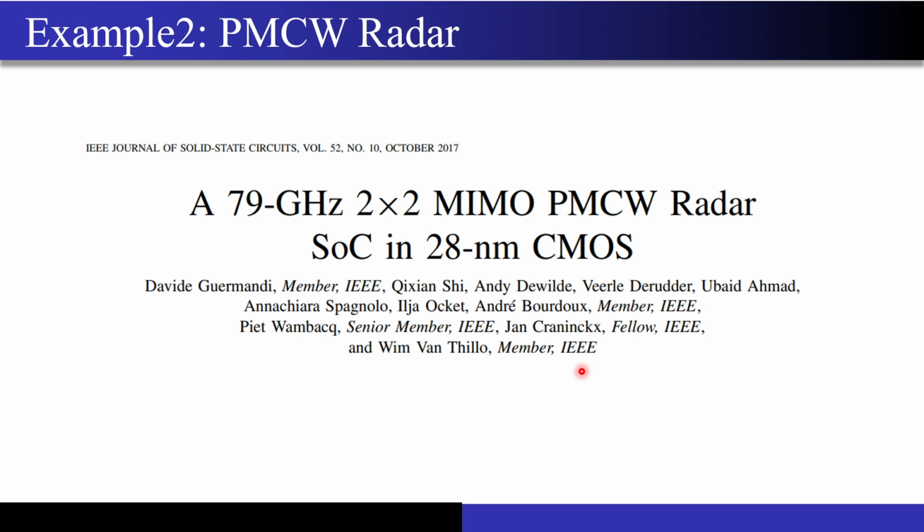So now if I move on to the next radar, that was the FMCW radar and this is a PMCW radar. What is the difference between the two? The reason is, as more and more new cars come onto the road, and as there are around 6 or 8 radars in each car, these radars will start interfering with each other. So in one particular scenario I receive a signal from somewhere and my radar interprets that as a target, but I come to know that there is nothing present in the environment, it is just the interference from another car's radar, correct?